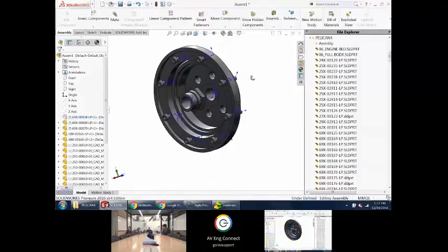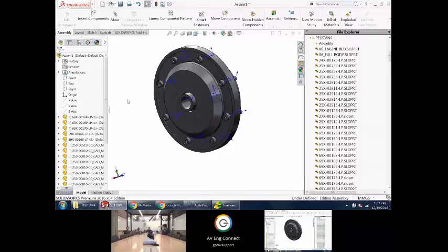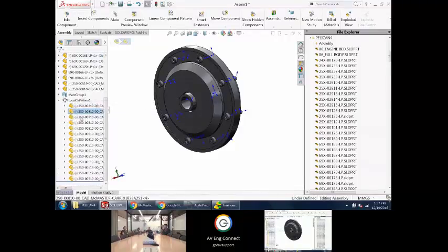If it's in a pattern, it'll still show up on BOMs that you make? Yes, it will still show up in the bill. Actually, let me undo this because you'll see that underneath the pattern, here's the actual components themselves. So they are taken account of, and when you get a bill, it shows the total count here.